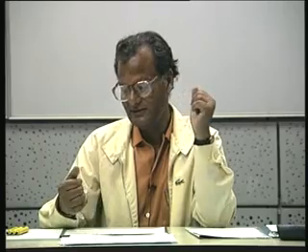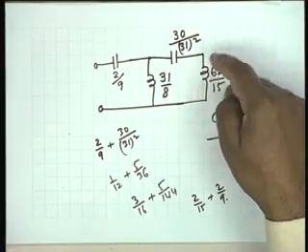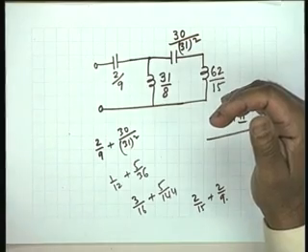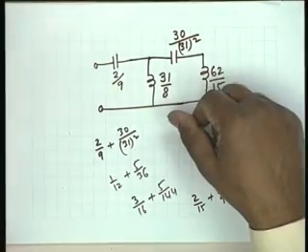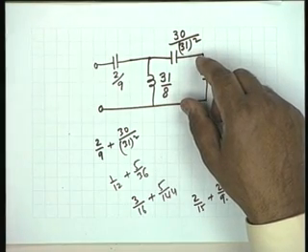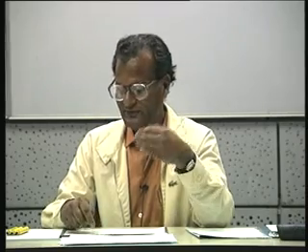So it's not just inductors, it's not just capacitors, it's the total structure that is important, and it depends on what you can realize in practice. Number 2: 31 by 8 or 62 by 15. 62 by 15 is more than 4 Henry. Who is going to make a 4 Henry inductor for you? Well, these are all normalized values. You don't require a circuit in which the resonance frequency is 1 radian per second. It will possibly be in the kilo or mega range, and therefore these values shall also be scaled down accordingly.